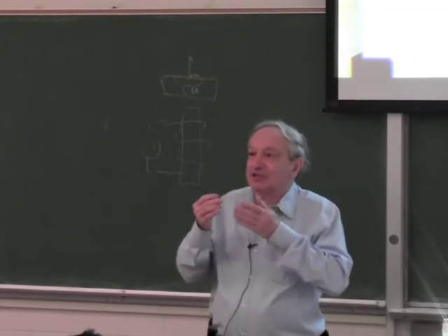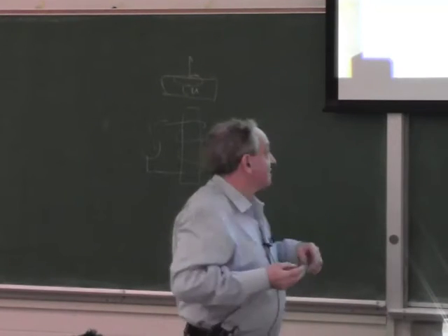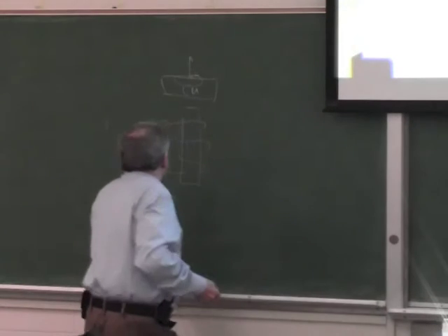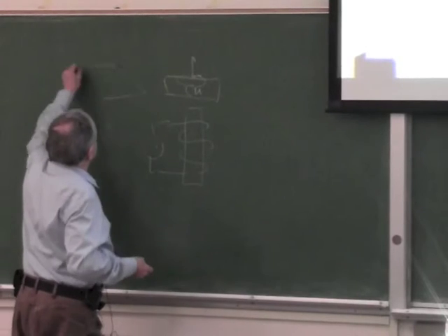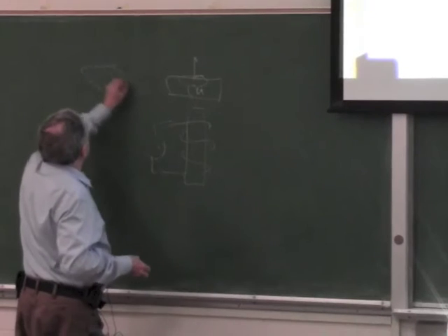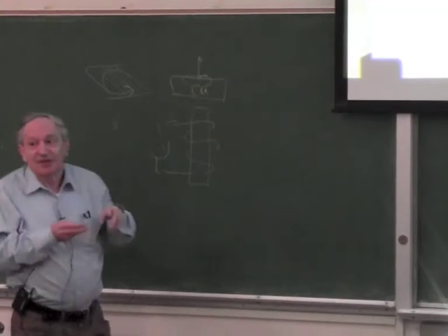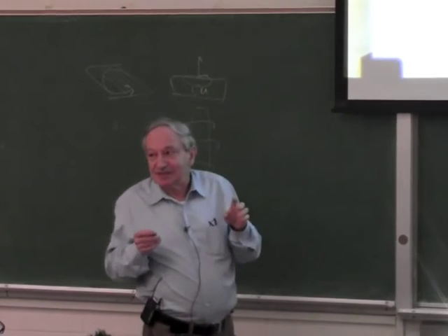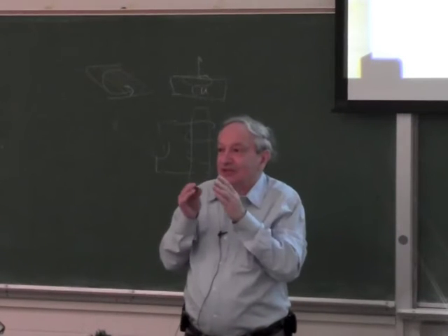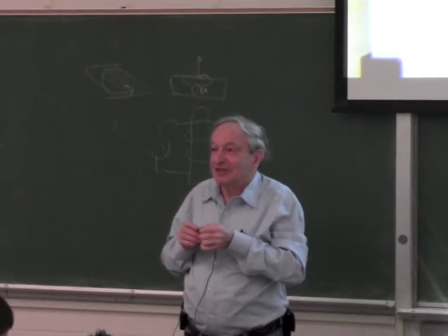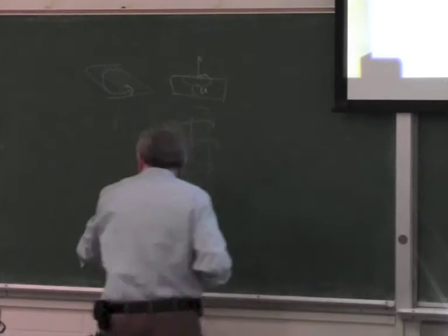Divided by laminations, because then you cannot have rotating currents. If this piece of steel here above the magnet is made of laminations, you cannot have a current going in a circle because it doesn't conduct. But magnetically it's still the same, as long as there's not much gap between the laminations. So it has to be laminated the right way, right?